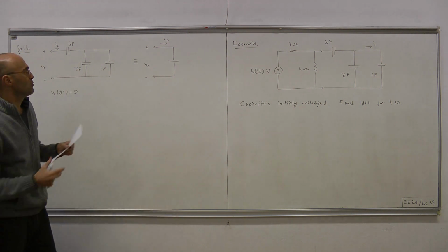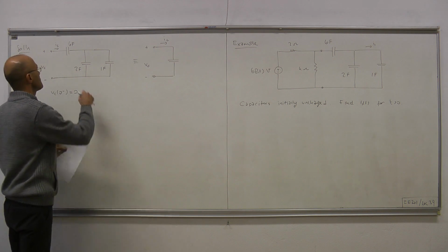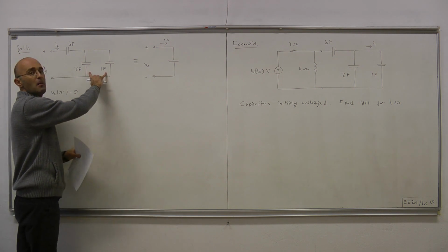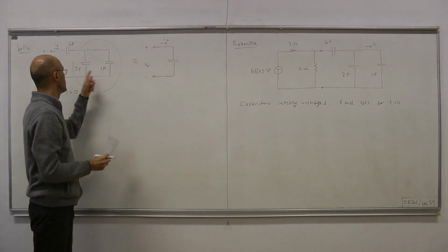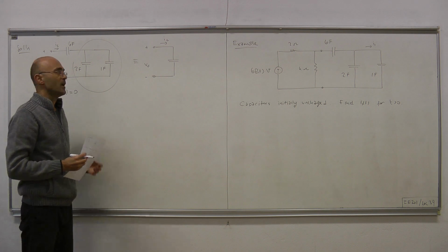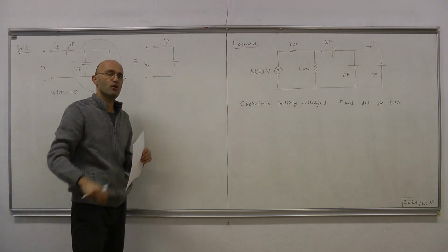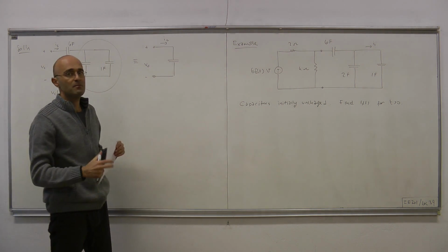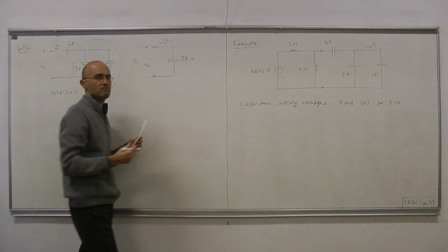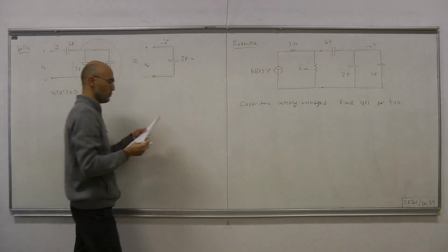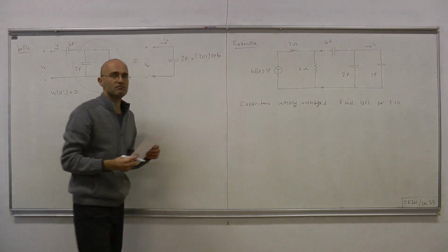And then we have to be careful about picking the capacitance of that capacitor. So what we have is 2 and 1, they are in parallel. Therefore, this bank can be represented by a 2 plus 1, 3 farad capacitor. And then we have a 6 farad capacitor connected in series with a 3 farad capacitor. And we know that the equivalent capacitance in that case is 2 farads. So therefore we have 2F as the capacitance, which we obtain by 2 parallel 1 and then series with 6.